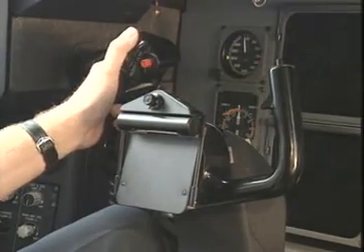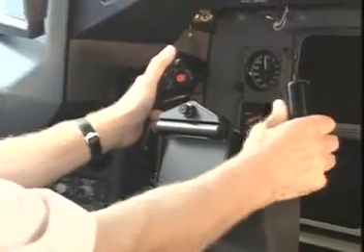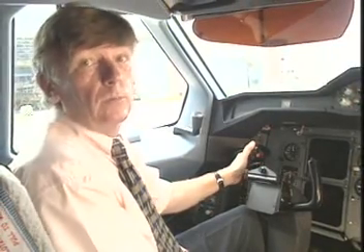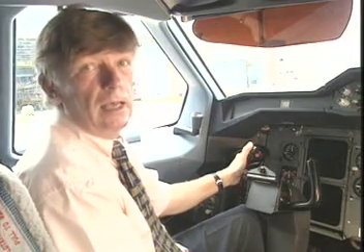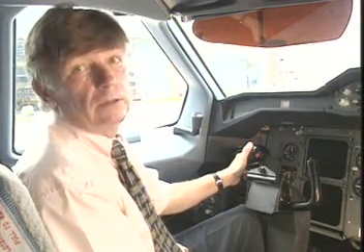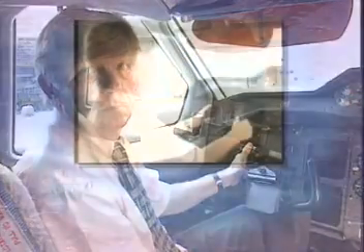A question naturally arises. How hard do I pull? Here are some considerations. Obviously, you must avoid impacting the terrain, but also avoid entering into an accelerated stall, and respect the aircraft's limitations of G-forces and airspeed.